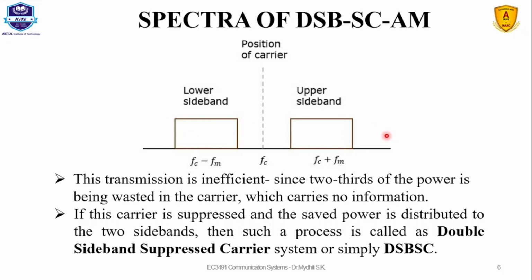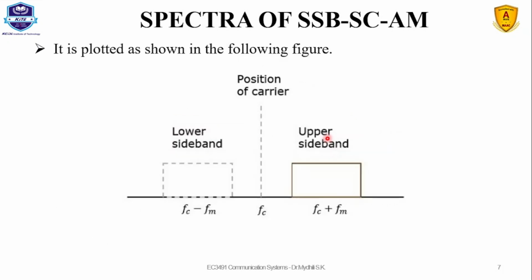We know that instead of carrying two apples, if we carry one apple, the weight will be reduced. Comparatively, with respect to power instead of weight, the power to carry the sidebands for transmission will be reduced when it is suppressed to one. So we are going to suppress the carrier as well as one of the sidebands.